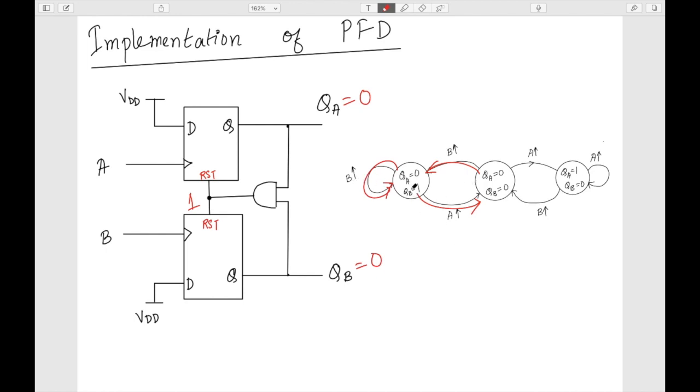If you are coming from this state to this state, you will see that there can be a momentary delay, because there will be a gate delay. First these two are becoming 1 and 1, and then this becomes 1 from 0, okay. And then the reset is fired. So from reset to Q there can be a slight delay. We'll understand this when we draw a waveform of this one, in the next page.